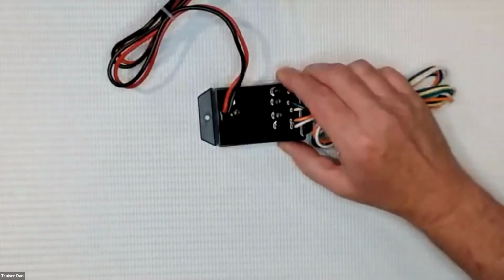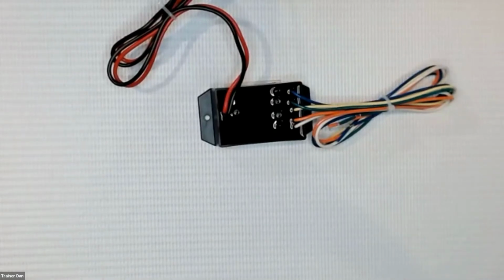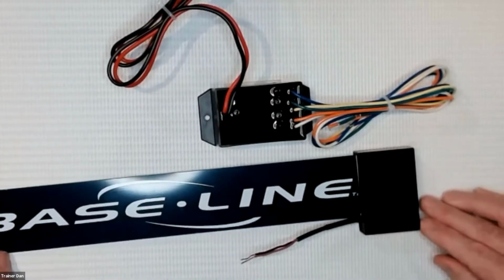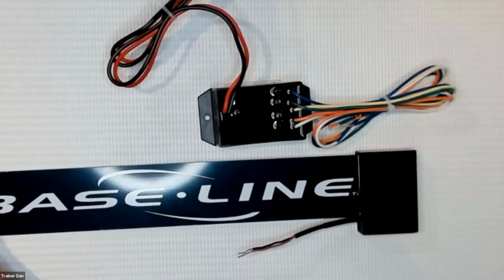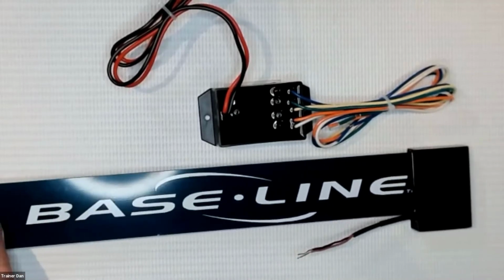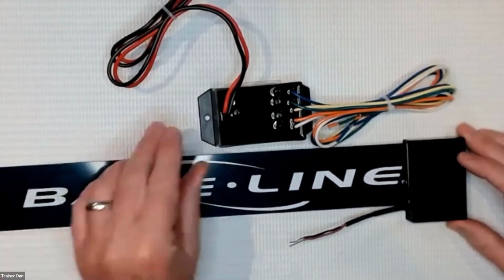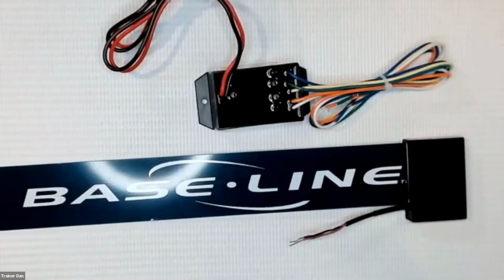So great. Okay. So the next thing down the path is going to be devices. So here's the valve bicoder and here's a soil moisture sensor. So two different devices that are going to connect on the two-wire path, although a soil moisture sensor can connect onto a conventional wire path. We're just going to talk about two-wire today.